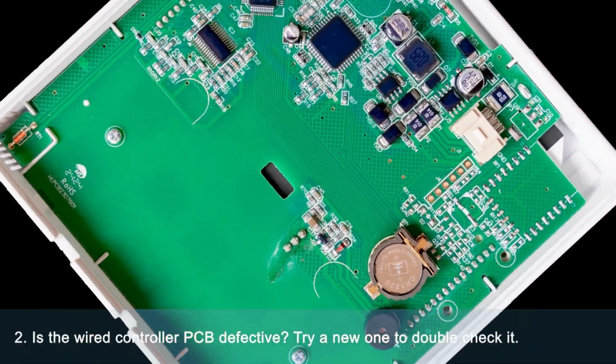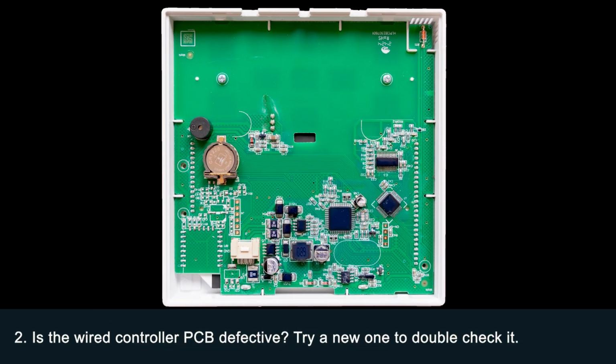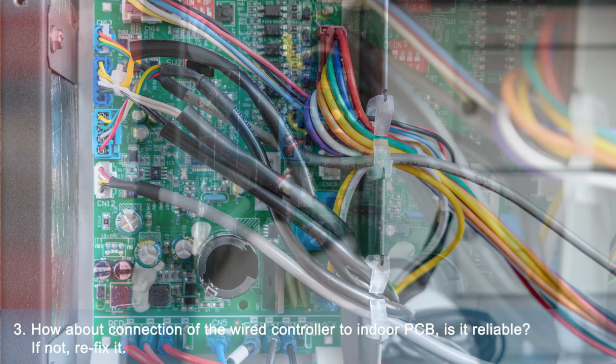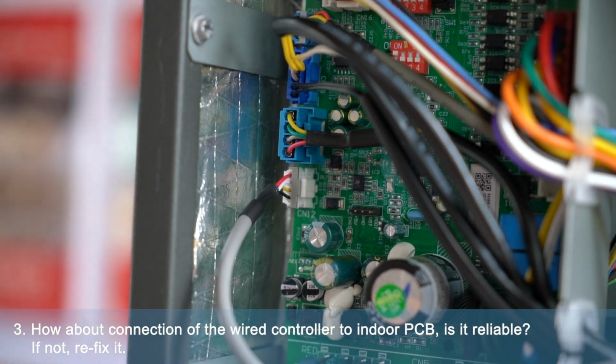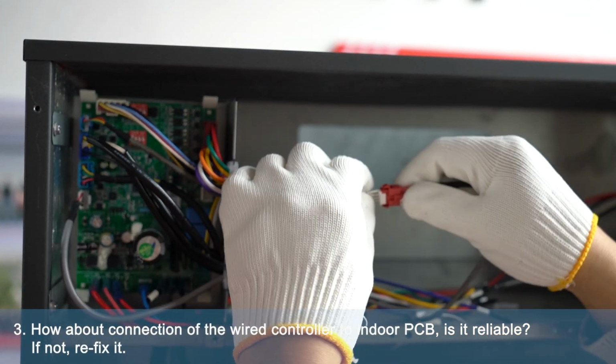2. Is the wired controller PCB defective? Try a new one to double check it. 3. How about the connection of the wired controller to the indoor PCB? Is it reliable? If not, refix it.